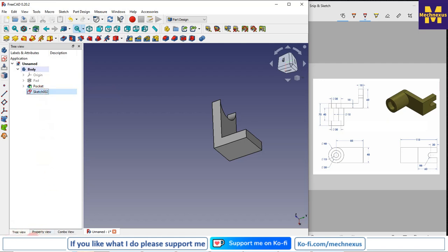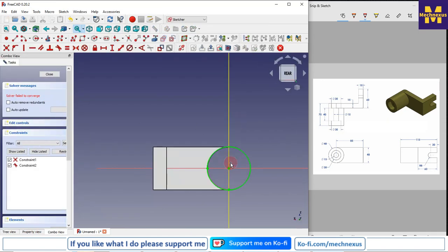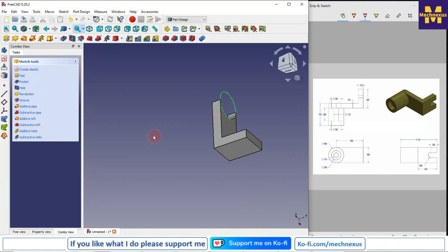So here is a problem that recompute failed. I will go again in the sketch and let's see what happened. I will delete it, and now I will select this and this and give it equal. I will say OK to the sketch and extrude it.